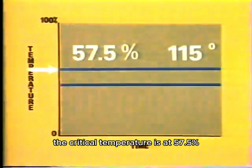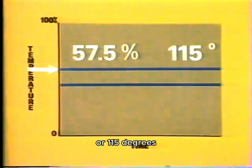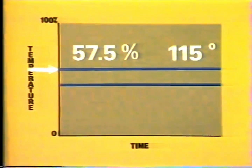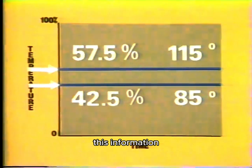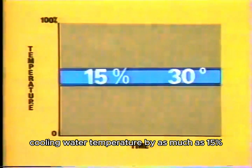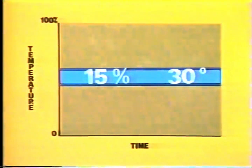The critical temperature is at 57.5%, or 115 degrees. The alarm will sound if the cooling water temperature gets this high. Set point is 42.5%, or 85 degrees. This information told the technician that he could vary cooling water temperature by as much as 15%, or 30 degrees, before the alarm sounded.